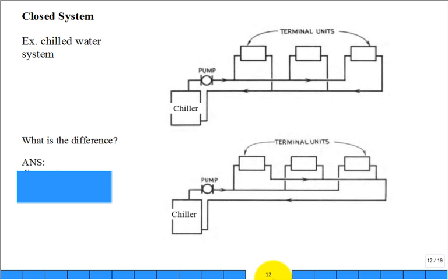The classic example is once I have that water chilled, in the chiller it would be on the evaporator side. That's the second loop going through the chiller. Then it's ready to go distributed throughout the campus, throughout the buildings. So this is going to be a closed system.